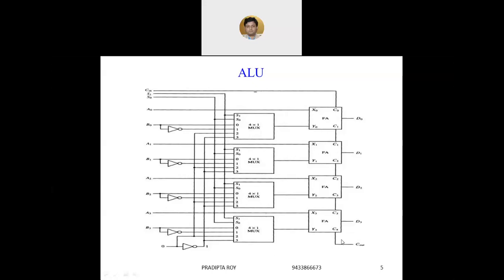With the same condition of S1 and S0, if we change the value of Cin to 1, that means we are able to perform addition with input carry. So, add with carry is performed here.